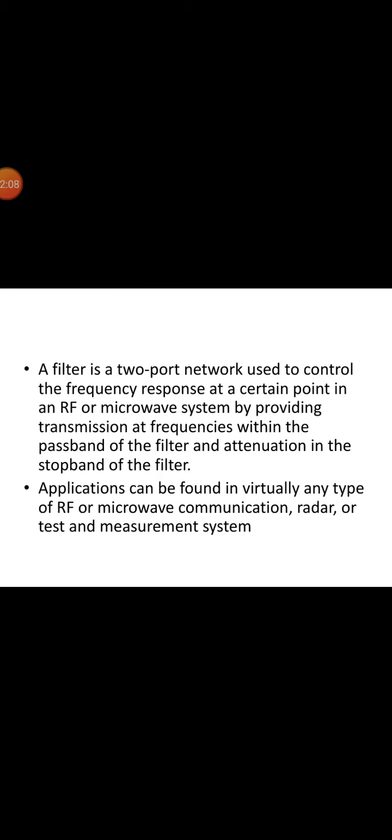Filters designed using the image parameter method consist of a cascade of simple two-port filter sections to provide the desired cutoff frequencies and attenuation characteristics, but they do not allow the specification of a particular frequency response over the complete operating range. Thus, although the procedure is relatively simple, the design of filters by the image parameter method often must be iterated many times to achieve the desired results.